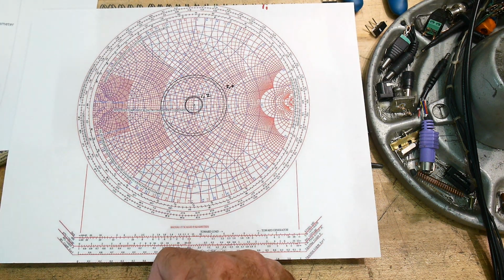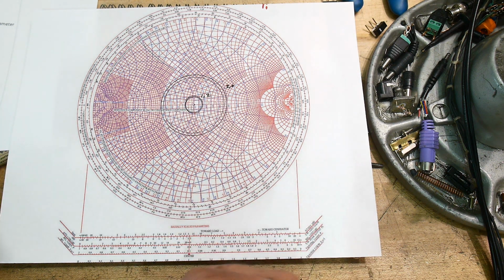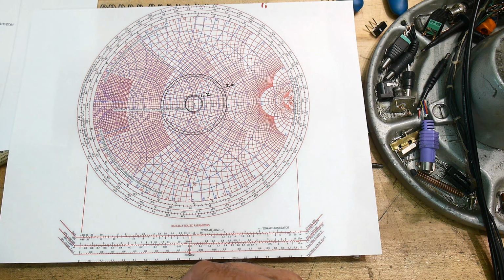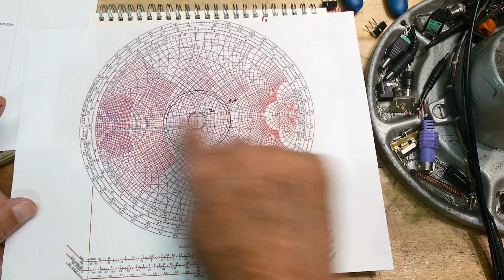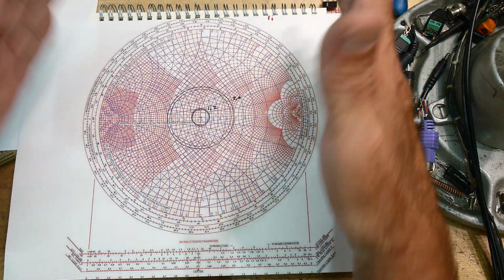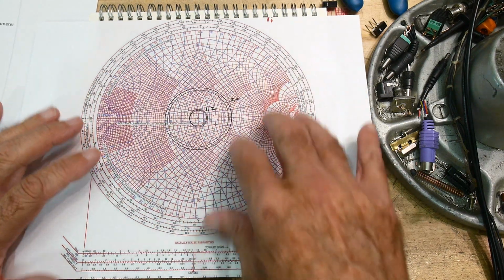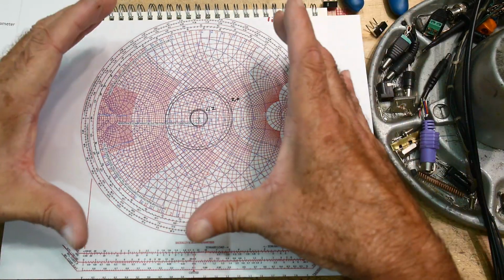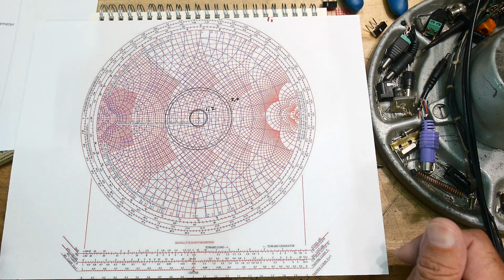So anyway, a long way around. I hope this kind of gives you an insight of what's actually in the Smith chart. It's actually a real gamma and imaginary gamma plotted in 2 dimensions, and then there's this overlay. There's these lines that are just kind of overlaid on top, and that's what the Smith chart is.